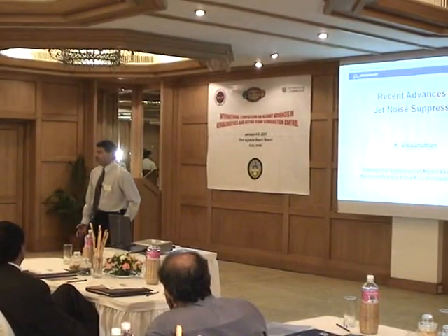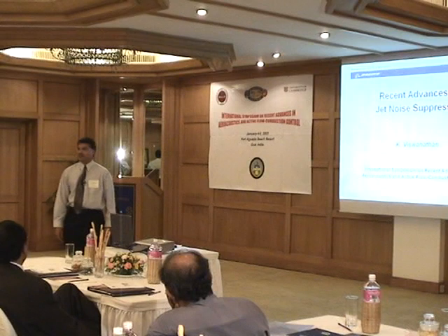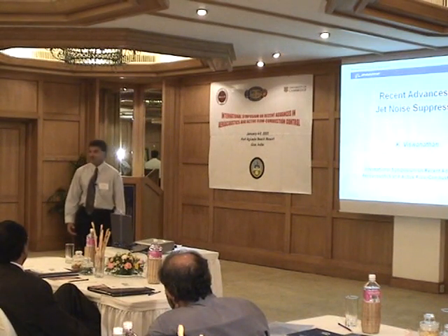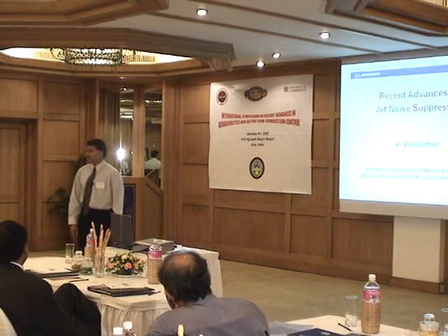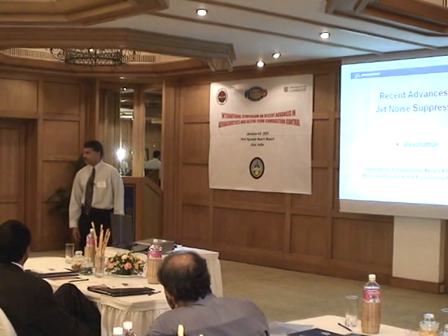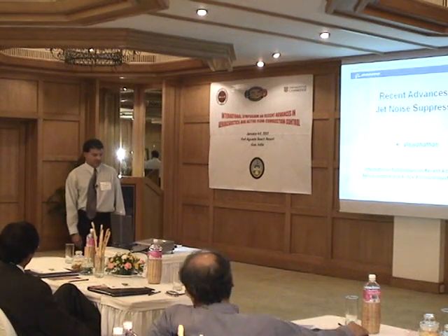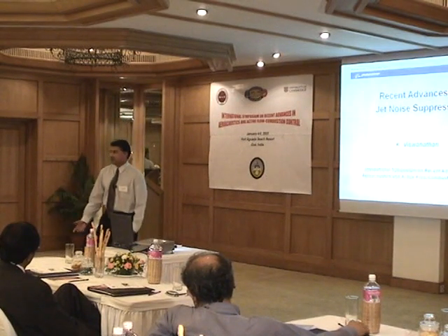to include the effect of source convection and showed that at very high jet velocities, the noise power scales at the third power of jet velocity, which is a very important result. Then there is the famous Ffowcs Williams-Hawkings equation, which is widely used to predict airframe noise and jet noise from computed flow fields. And finally, there are many other things which you'll be hearing from the other presenters in the next